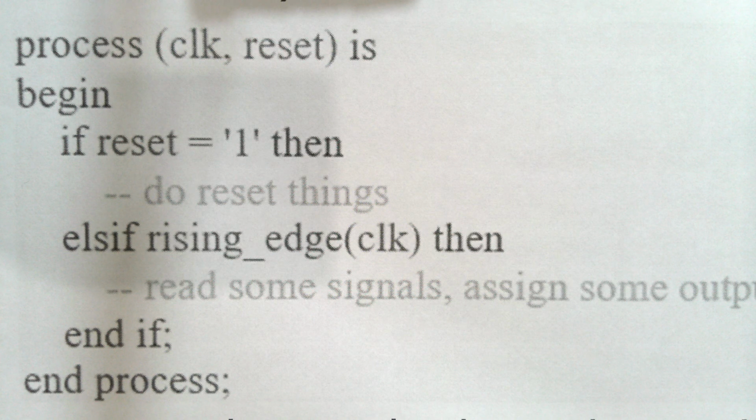So any port that is not aligned with the clock needs to be in the sensitivity list, because if we do not put it in the sensitivity list, when changes occur to that port, the process will not be notified of that change and your system would not operate as it's supposed to.